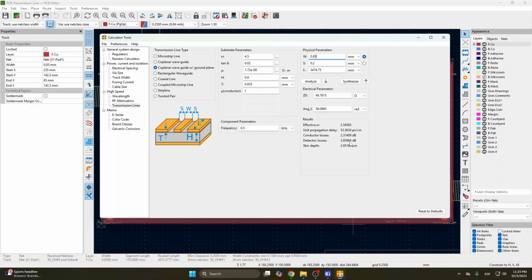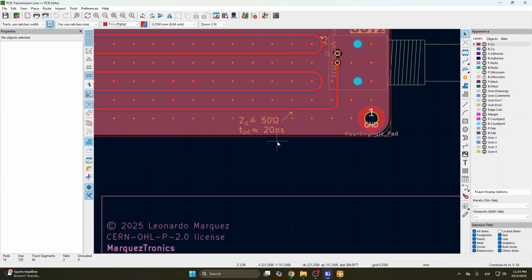If we take into account the BNC connectors, the cables that we are using to connect the board to the oscilloscope, our total propagation delay observed in the experiment is going to be probably closer to 20 nanoseconds. And that's why I have labeled in my silkscreen TPD, or time propagation delay, of approximately 20 nanoseconds.